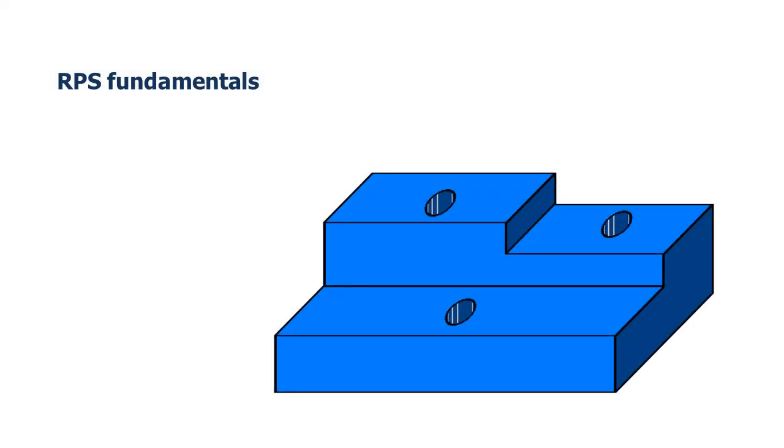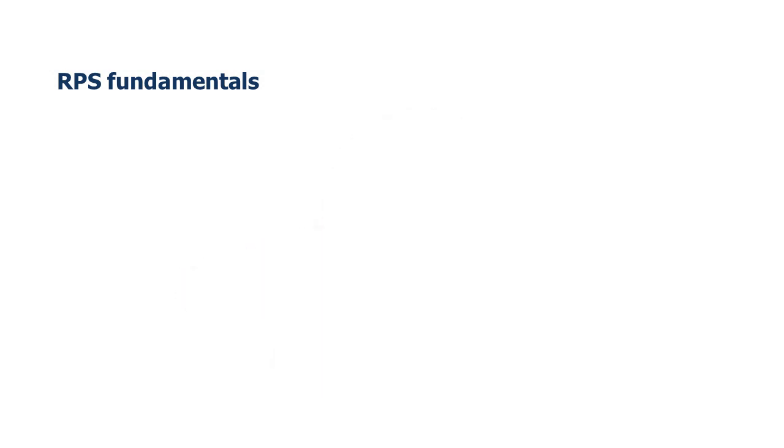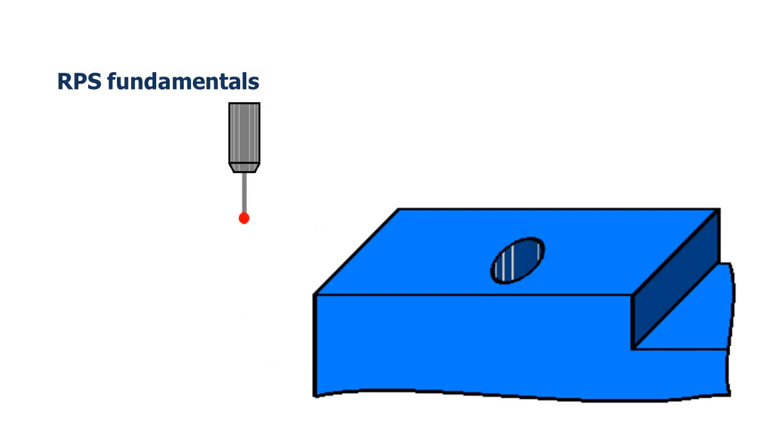As mentioned earlier, with an RPS alignment you need 3 features that capture the X, Y and Z positions accurately. With these 3 points you can perform a type of 3, 2, 1 alignment. First, let's consider the plane feature. The measurement of each of the 3 holes using the non-aligned circle method captures each hole's center position and the adjacent surface position.